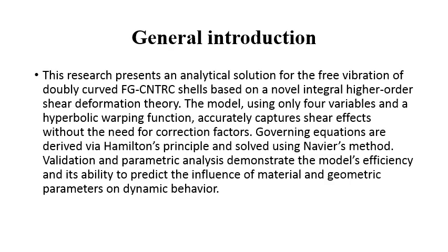This research presents an analytical solution for the free vibration of doubly curved FG-CNTRC shells, based on a novel integral high-order shear deformation theory. The model, using only four variables and a hyperbolic warping function, accurately captures shear effects without the need for correction factors.